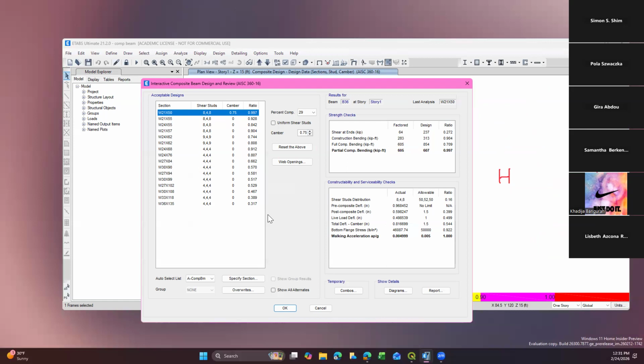So it's not 30, because the girder is spanning from here to here, right? They use a length of 30 feet minus half of the column, maybe roughly 1 foot off. So they may use 29 feet as the main span, then 29 minus 10 divided by 2, so 9.5 times 64. Yes, roughly 605; I got 608.